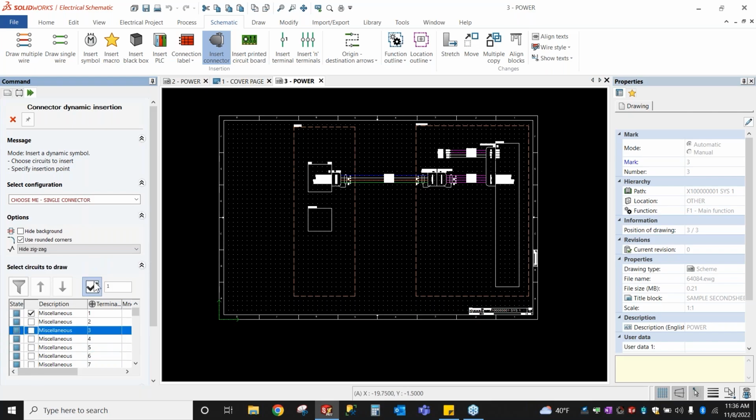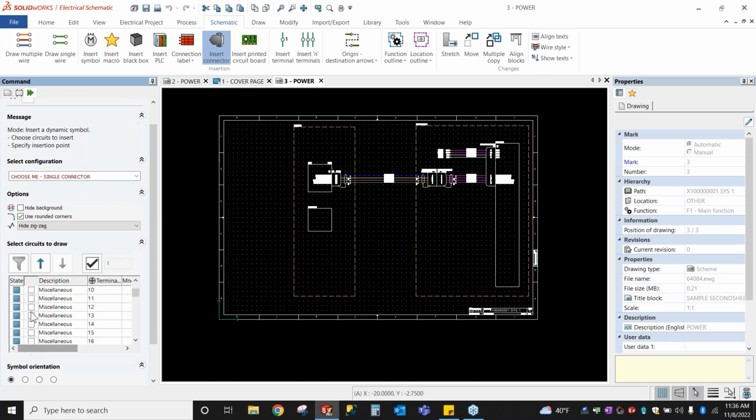Am I insane? That's because this filter is only limiting you to be able to select one pin at a time. You could increase that number if you'd be like, hey, I need to select 10 pins. Don't let me select more than that. You could do that. Or you could just click it again and turn it off, and they're still deselected, but then you have freedom to select multiple ones at a time.